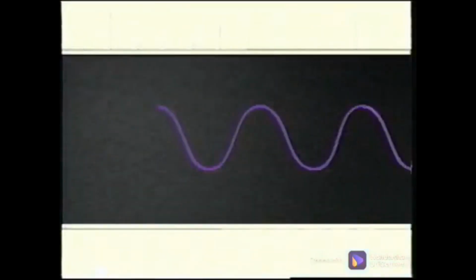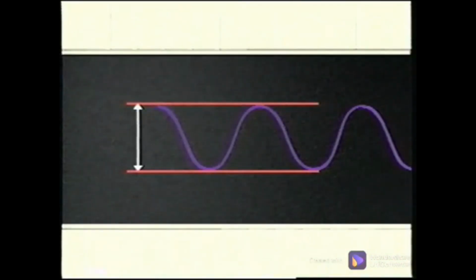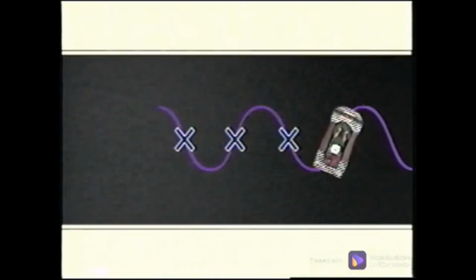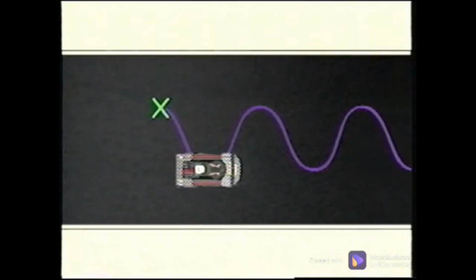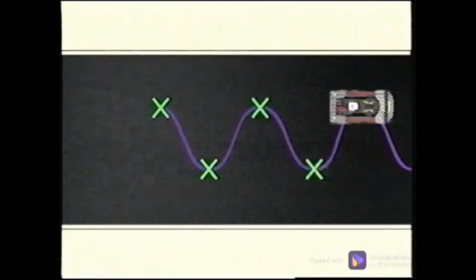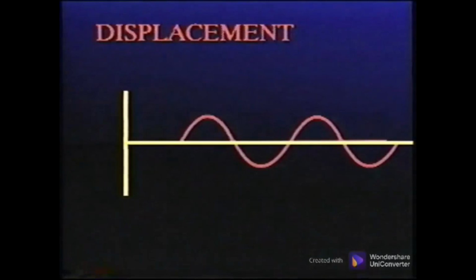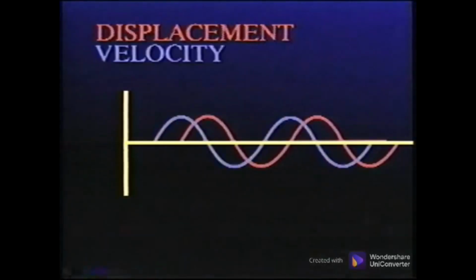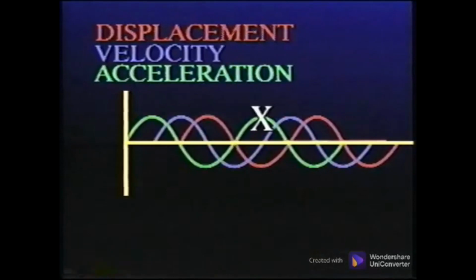In another program, Introduction to Vibration Analysis, we use go-karts to demonstrate that a waveform can show three precise measurements. The displacement measurement is the total distance traveled from one peak to another. The greatest speed, or velocity, is at the midpoint, and the greatest acceleration is at the turning points of the waveform as the direction changes. Each measurement of displacement, velocity, or acceleration can be displayed as a separate waveform simply by displaying the maximum velocity or acceleration at the top of the waveform.